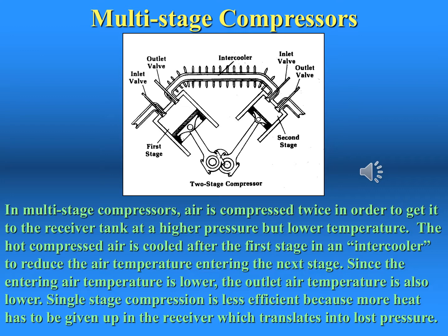enters the receiver tank. Air is compressed first in a larger stage and then sent through a heat exchanger called an intercooler. Remember that heat will transfer to any surface with less heat. This is how the intercooler works. In the intercooler, heat is transferred through the walls of the intercooler into the airstream that blows over the intercooler as provided by a fan.